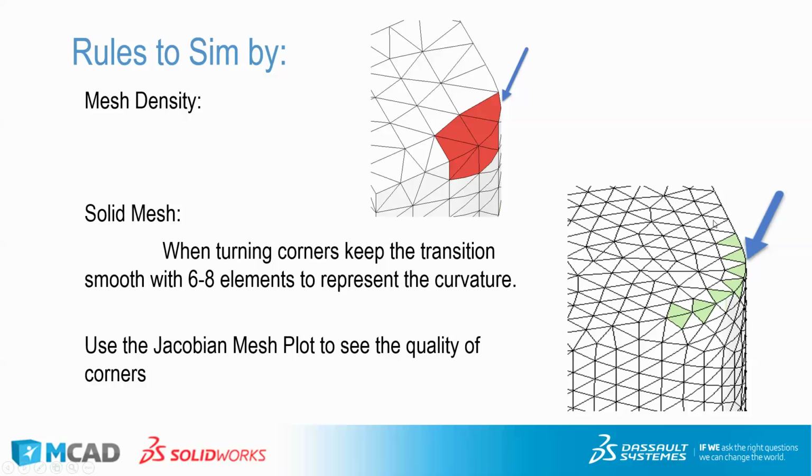And the way we get that nice transition is using a curvature-based mesh, which, as you can see here, will attempt to get a certain number of elements around the corner rather than just kind of haphazardly recreating the corner. It'll actually try and faithfully reproduce that edge there, that circular edge. All right, let's see how SolidWorks is doing as far as getting restarted here.